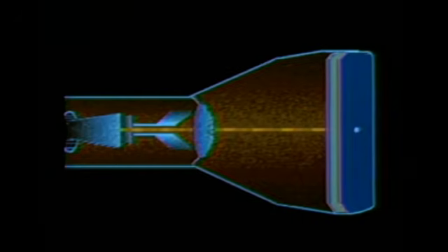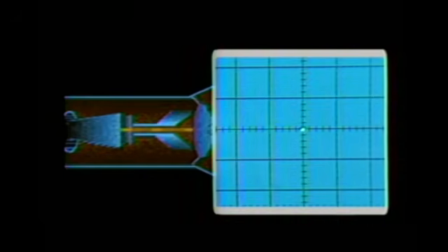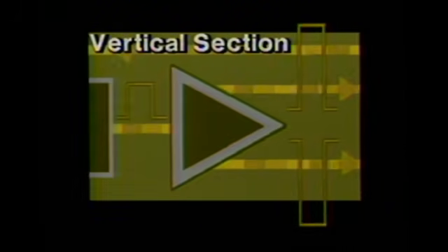For this discussion, let's assume we have a CRT with a vertical deflection sensitivity of 10 volts per division. So to move the signal up one division, instead of attracting it with a 10 volts positive signal, we can apply a 5 volts negative signal to one deflection plate, which essentially pushes the beam away, and apply 5 positive volts to the other deflection plate to pull the beam. This concept is called push-pull. The process is used primarily to improve the linearity of the display and allows accurate measurements over the entire viewing area. Push-pull signals are equal in amplitude and opposite in polarity.